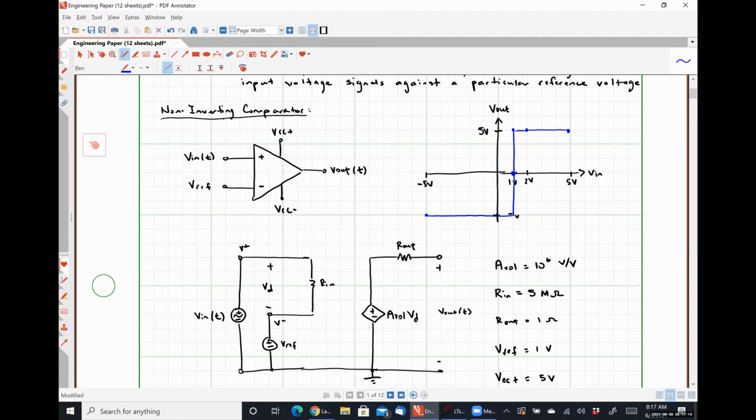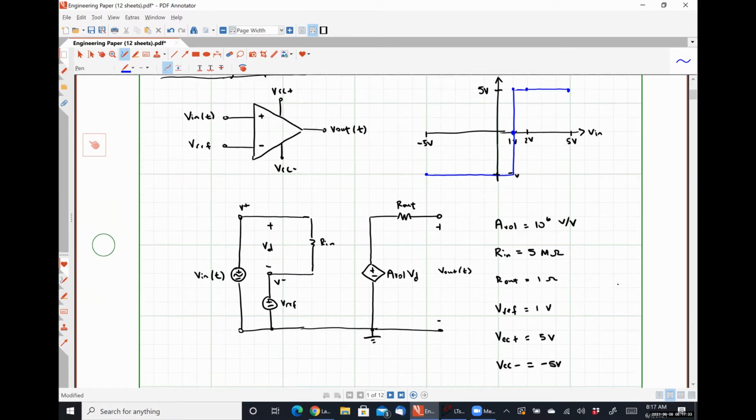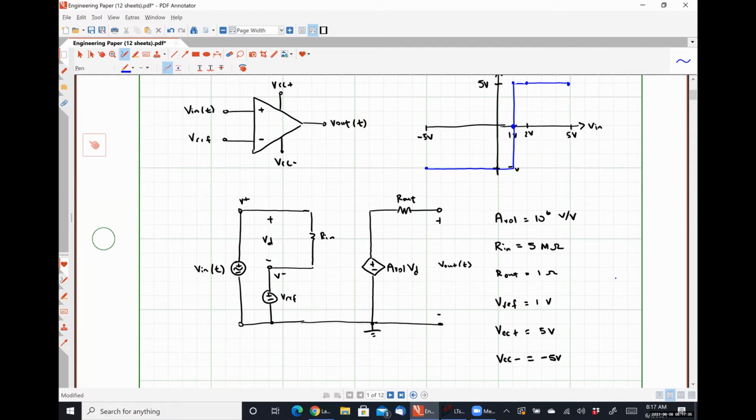So the linear range on this guy is literally from -5 microvolts to +5 microvolts. Anything outside of that range causes saturation. So this is going to have an incredibly steep slope in that small transition period. So we can infer a good enough approximation of how this particular device behaves, right?